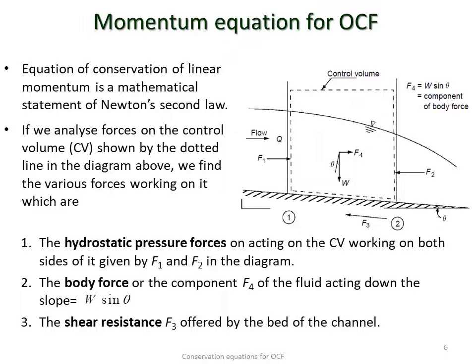Now from the equation of continuity or equation of conservation of mass, let's move on to the equation of conservation of momentum, or momentum equation for open channel flow. We know that momentum is a vector quantity, of course, and we also have discussed many times that the equation of conservation of linear momentum is a mathematical statement of Newton's second law.